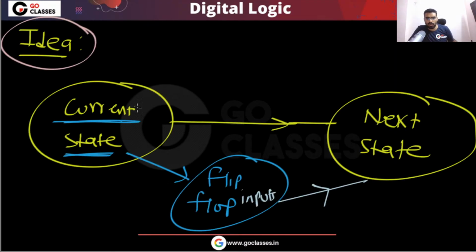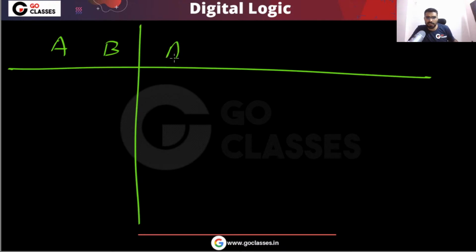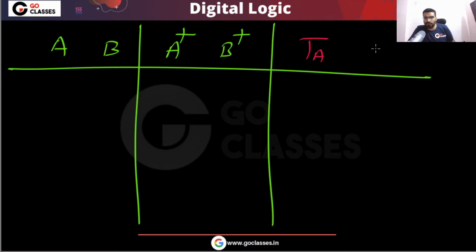This is the idea we will follow. You are in the current state, and from the current state you will find the next state. Your current state is A, and this B is also your current state. The next state means A next, B next. And you can notice these are the flip-flop inputs, TA, TB.